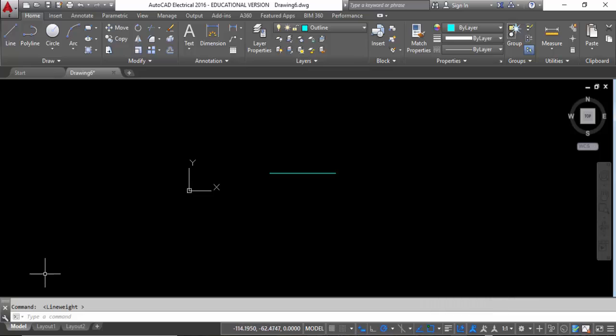I prefer utilizing just the scales on the layouts and having my annotation then set to the layouts, if I've got different windows in the layouts and various dimensions with different sized text. And what do I mean by that? If I've got a 3mm size text or a 5mm size text, I can then place that onto the layout, which is basically your paper layout.